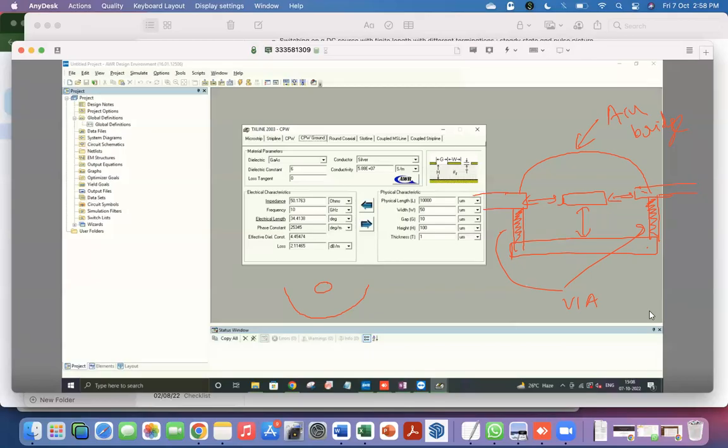Sort of. So because the dielectric constant is high there, that part of the structure is going to contribute to the capacitance more, because it's going to be 10 times higher than the capacitance through free space for the similar dimensions, right? So changing the height will affect the capacitance per unit length a lot more than changing the width.